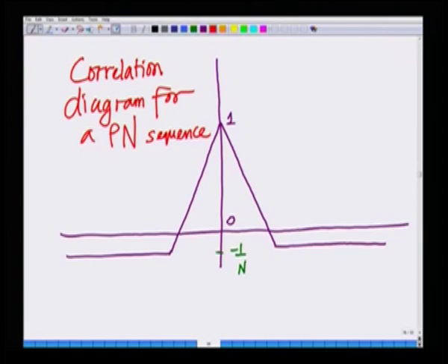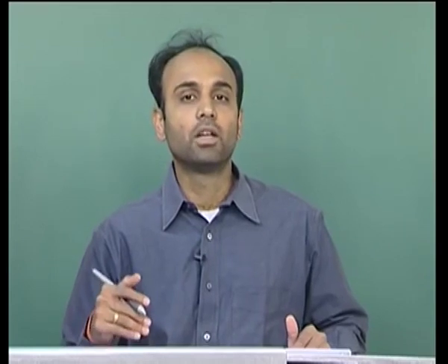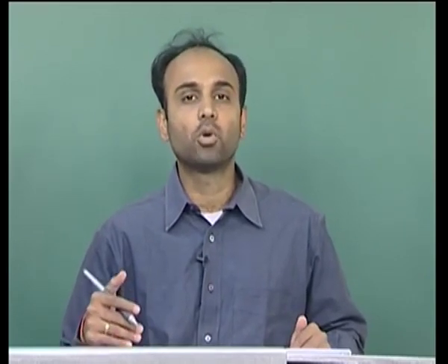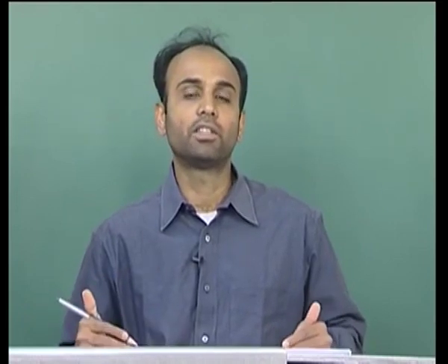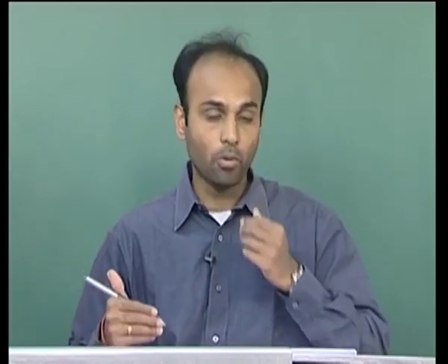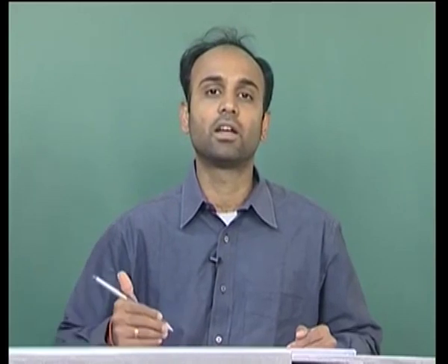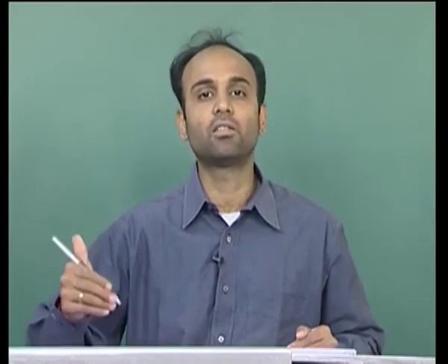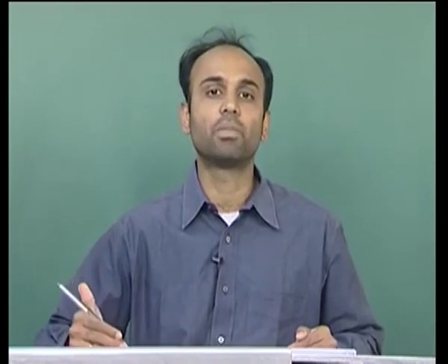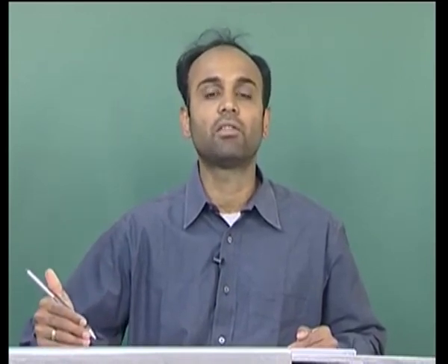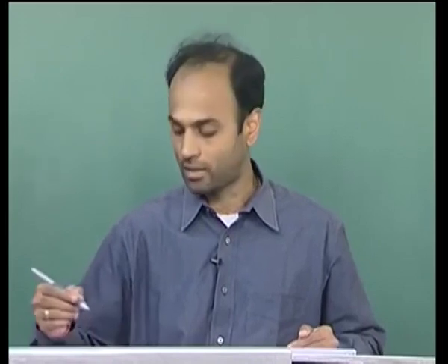Okay, so, this is how the correlation structure looks for a PN sequence, and it is important to keep this in mind, because such PN sequences and such codes form the heart of every CDMA system. They are the key component of every CDMA system. Hence, it is very important to understand the properties of these PN sequences in detail. Hence, I urge you again to go back, take a look at the several properties that we have discussed in PN sequences regarding linear feedback shift registers and the length of the sequences and the properties of the PN sequences generated by these linear feedback shift registers or LFSRs. Okay.